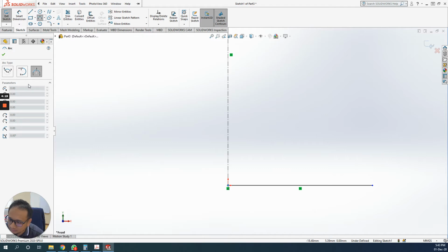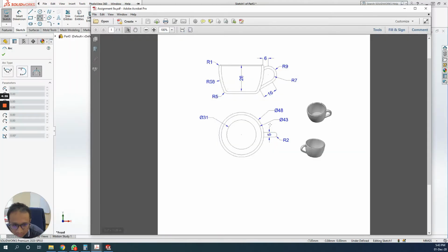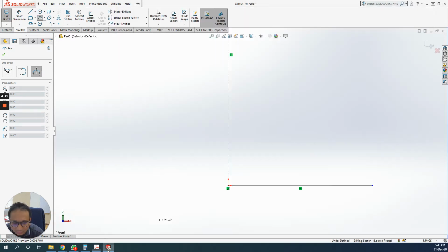millimeter radius, you can draw using either this one, the 3-point arc, or a tangent arc. So a 3-point arc is, first you draw the circle, and then you take the length. Since you know the length has to be around 5, basically it's about 5 mm towards the top.